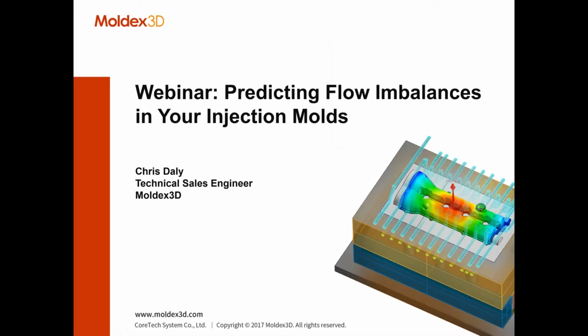Predicting flow imbalances in your injection mold. What I'm going to cover today is mostly around multi-cavity systems and the type of imbalances you can have, whether it's a geometric imbalance, a shear-related imbalance, or related to the heat transfer in your mold.